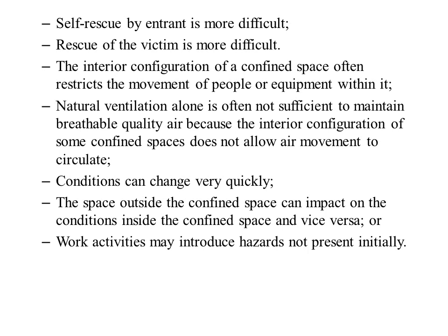The interior configuration of a confined space often restricts the movement of people or equipment within it. Yes, we agree that natural ventilation is often not sufficient to maintain breathable quality air, because the interior configuration of the confined space does not allow air movement. As the space is very small, the movement of air will be very difficult. Because of that, natural ventilation is not possible. And in a confined space, the conditions can change very quickly. The person who is entering a confined space may feel safe at the beginning, but that situation can change very quickly.